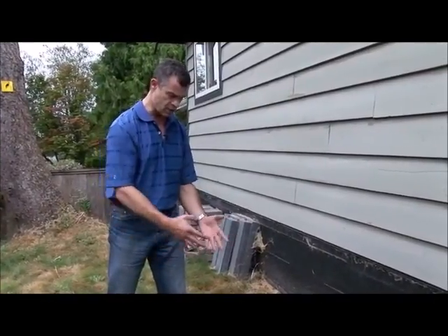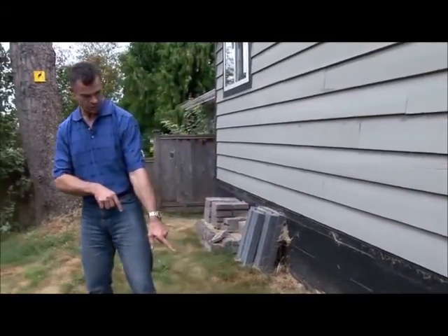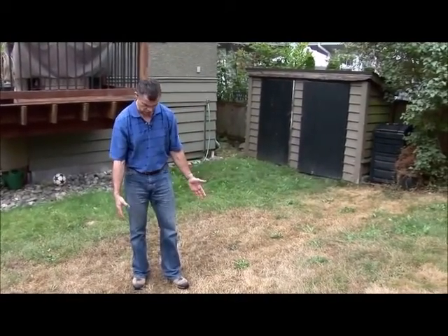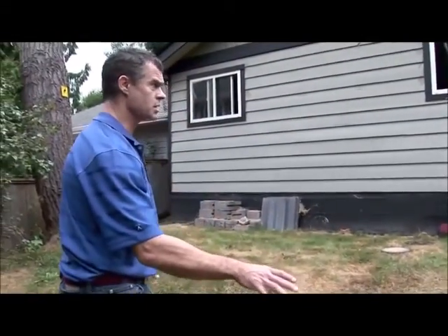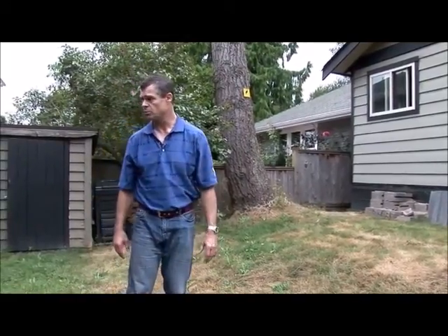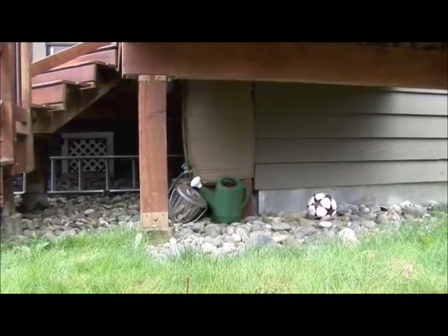So during heavy rains, if this sump fills up and the ground and the water is saturated, the water comes out from a pipe that flows down here and flows into my main backyard infiltration system. So this system here has allowed me to build the garage and all the parking lot with no connection out to the storm sewer system. So after working with the city, I got all of the approvals that I needed to put that alternative system in place. Bowes also has a rain barrel connected to his house.